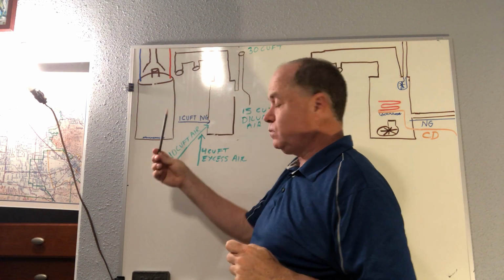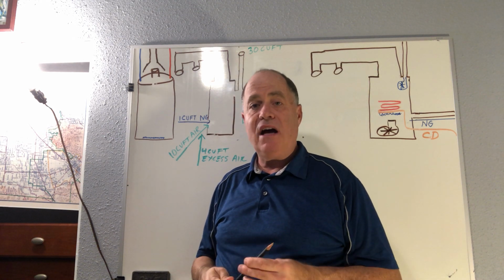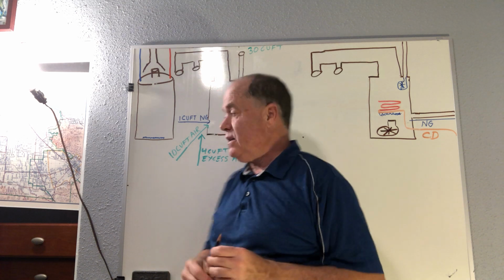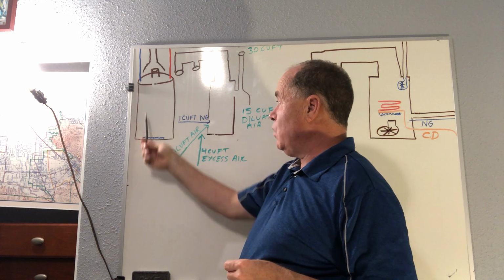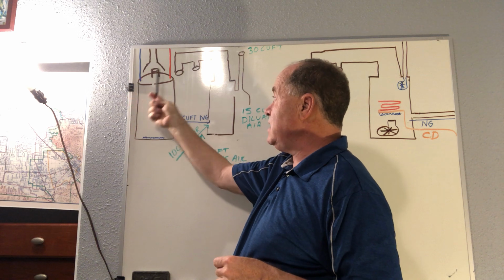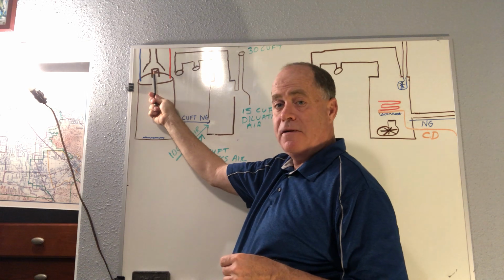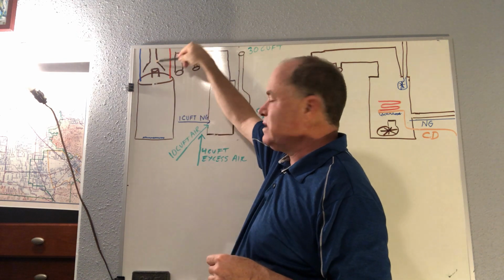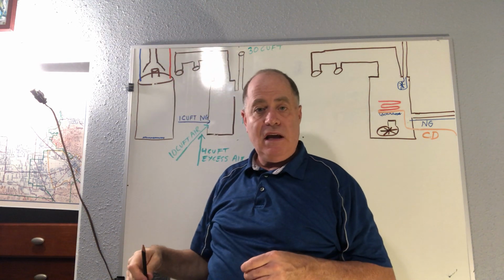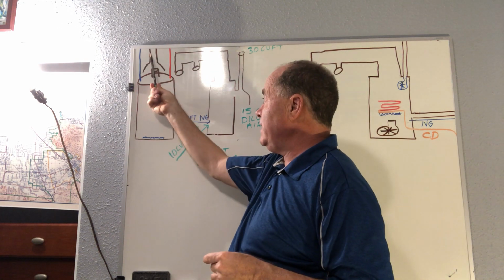So first here, one appliance that is still absolutely designed this way with natural combustion air is a hot water heater, where you have the fire down here, and the cold pipe comes in and the hot pipe comes out, and then the products of combustion come out the flue pipe. Then you have this thing that sits on top where there's a little air gap, and then the vent pipe goes up and either out of the building or over the top of the roof, and that's your vent pipe.